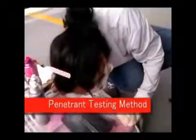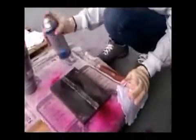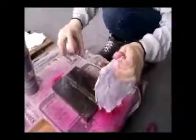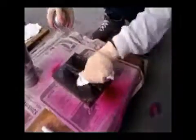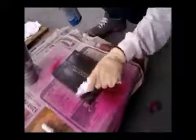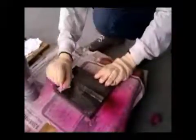Visual inspection, or visual testing, is the process of looking over a piece of equipment using the naked eye to look for flaws. Paint, oil, grease or any loose scale could either keep penetrant out of a defect or cause irrelevant or false indications. Cleaning methods may include solvents, alkaline cleaning steps, vapor degreasing, or media blasting. The end goal of this step is a clean surface where any defects present are open to the surface, dry, and free of contamination.